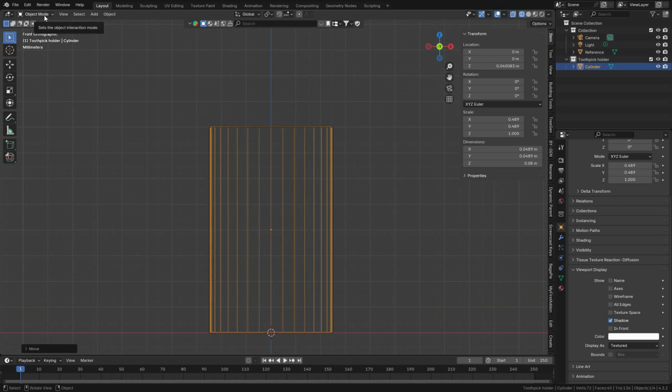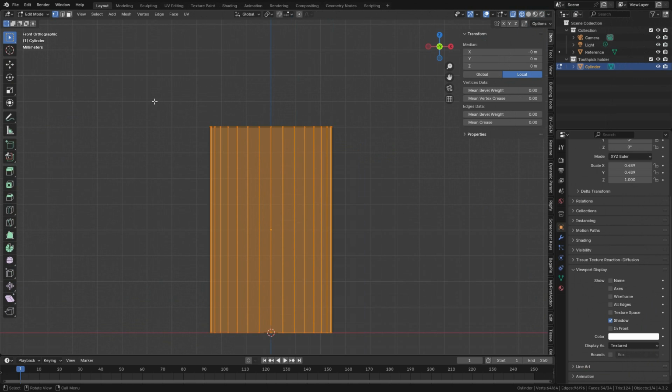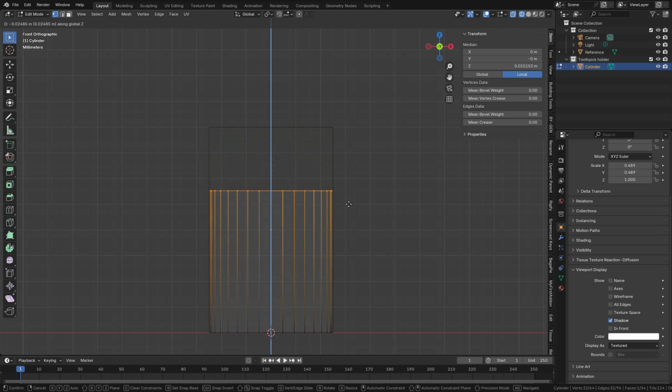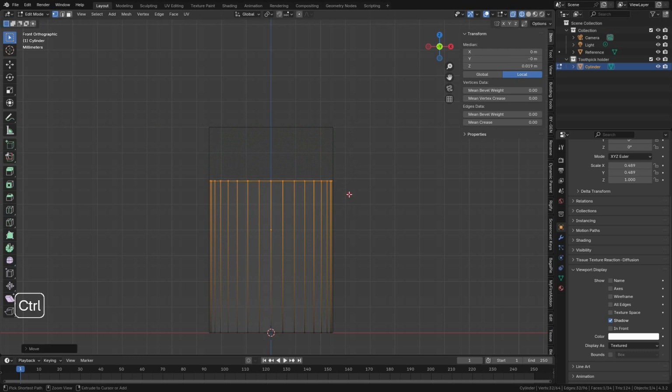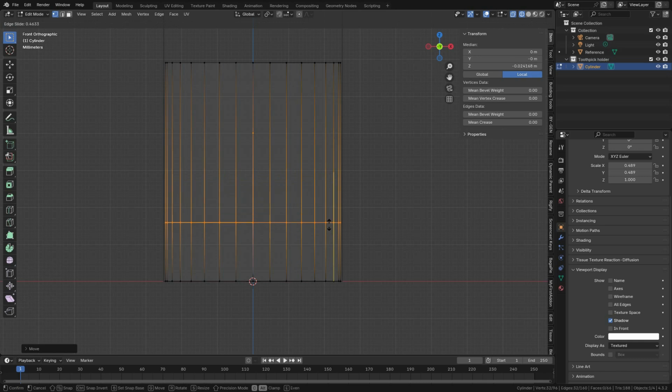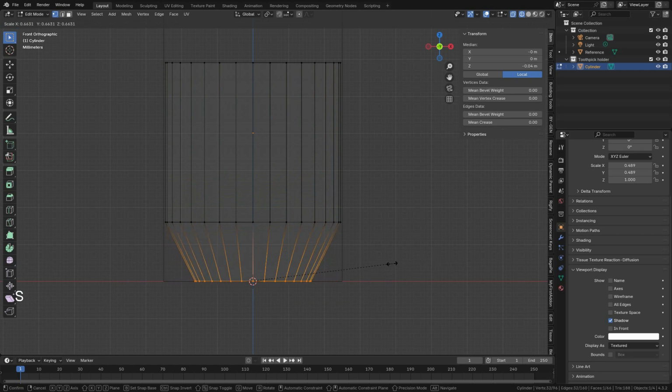Okay, you go to edit mode. Select this, holding left mouse button, and then you drag across this place. Then bring it down on the Z axis by pressing G then Z, and just bring it to about the average height of the toothpick jar, which should be about here. Holding Control, now just click to confirm. We add the loop cut here, left click, drag it down. I think about here should be okay. We select the bottom here, press S and scale it in. So somewhere here.